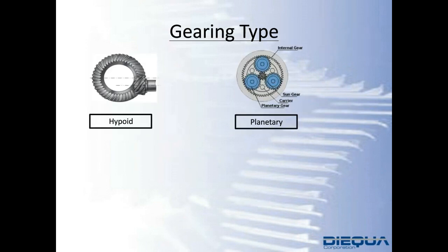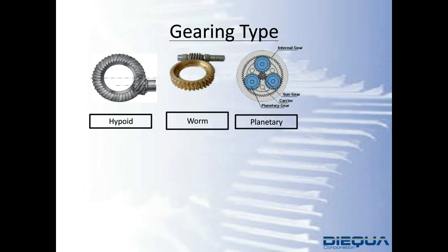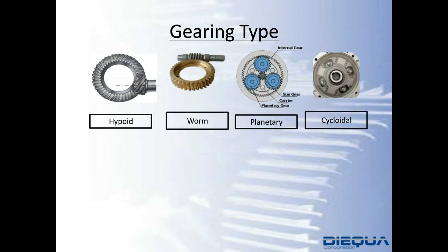Excellent. All right. So all along we've been talking about the benefit of having linear motion in a system, how we start off with a rotary supply from a motor, and how a reducer gearbox, gear unit if you would, help reduce the size of the motor while giving you more torque, give you an output speed that's lower but still ideal for what you're looking for, and how the reducer itself could offer up an output connection to connect to your machine.